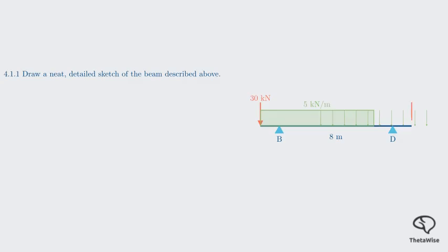Then there's a point load of 40 kilonewtons at the right end, which is at x equals 8 meters. Finally, we have another point load of 40 kilonewtons 2 meters from the right end. This is at x equals 6 meters. This gives us a load of 40 kN at x equals 6, exactly where the UDL ends. So, let's update our diagram to show these 2 loads combined at that specific point.